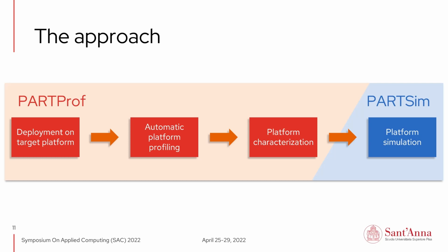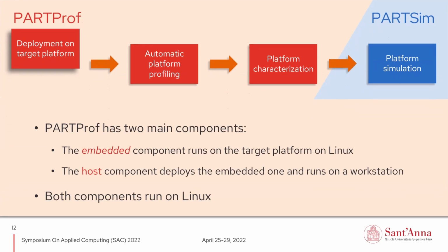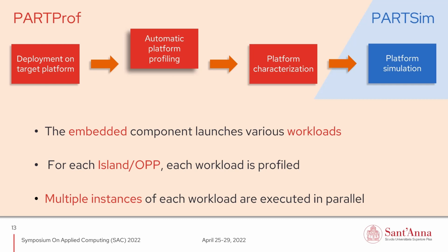by a few steps. In the first phase, the profiling suite is deployed on a target platform, on which it performs a set of automated profiling runs. The component that gets deployed on the target platform and performs the actual profiling is called the embedded component. In contrast, the host component typically runs on a workstation and manages data post-processing. Both software run on Linux platforms. The embedded component can be configured to execute a set of actual real-time workloads on a target platform under various DVFS settings.